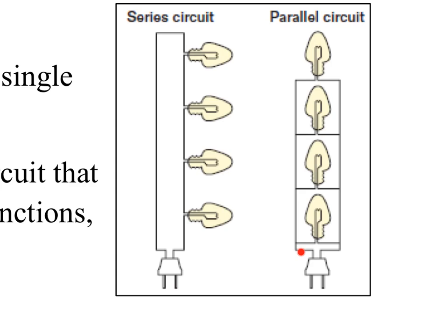This is like the flow of water coming through and then the water splits. Part of the water goes here, part of the water goes here. So this current goes into this bulb and comes right back to the source. But part of the current splits. It goes here, goes into this bulb, and joins back up to the source. Part of the one that went here split and went up here, and part of that goes into here and comes back. The rest of it comes out here and comes back. But notice that these two rejoin right here. The current from all these rejoin with this current down here at the bottom.